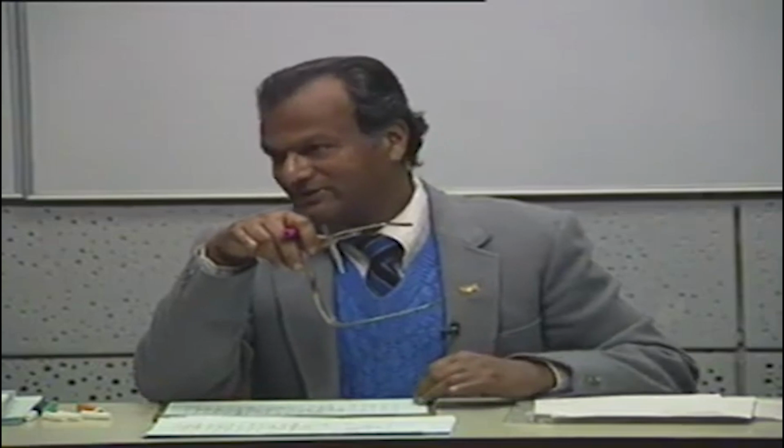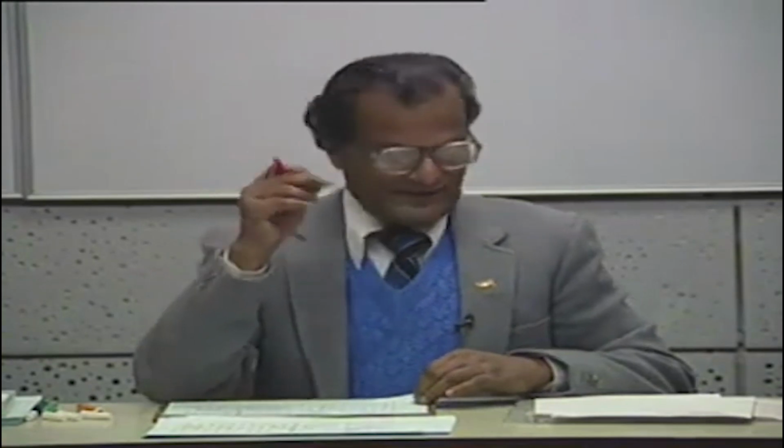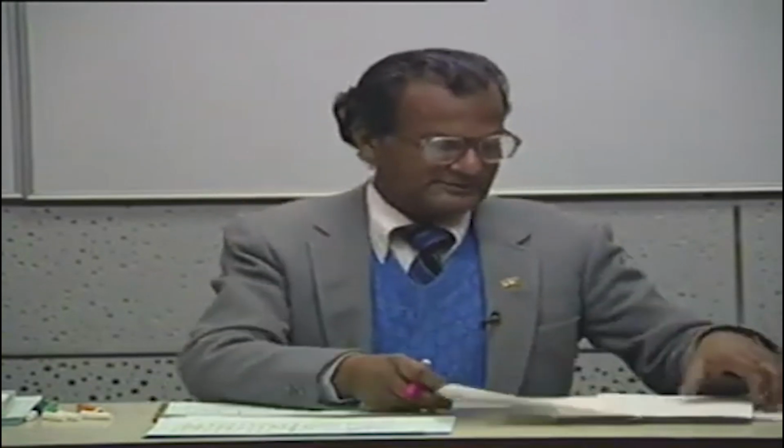It's very loosely said, it's not exactly 0, but since the value is less than the accuracy of an instrument available in the laboratory, we say that for all practical purposes an exponentially decaying waveform has decayed to 0. It means it is dead after 5 times the time constant, and that's why we say the lifetime of an exponentially decaying waveform is approximately 5 times the time constant.